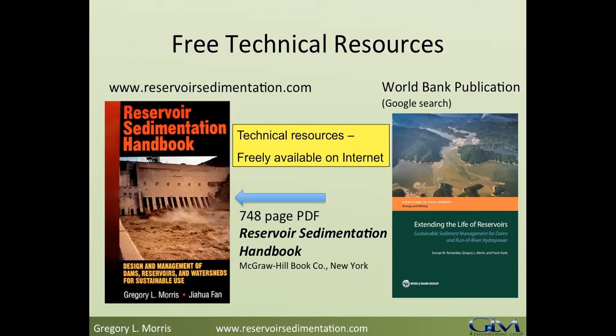Now, in some rivers, the Rio Grande, for instance, there are multiple diversions, and you're basically draining all the water out of the river, and you end up with insufficient water to transport sediment. But typically, where you would use an off-stream reservoir in a moist climate, that is not typically an issue.